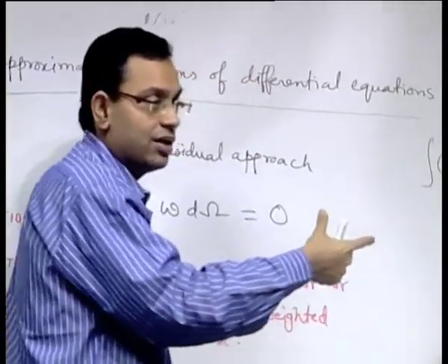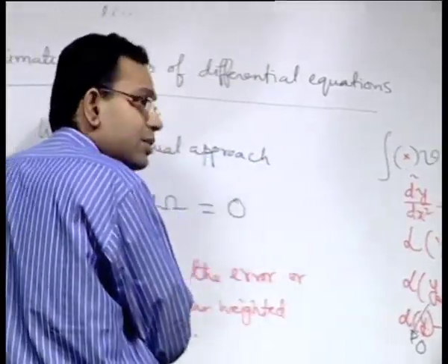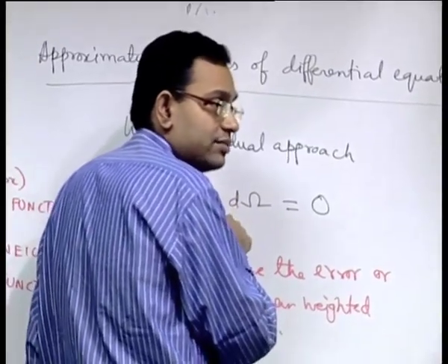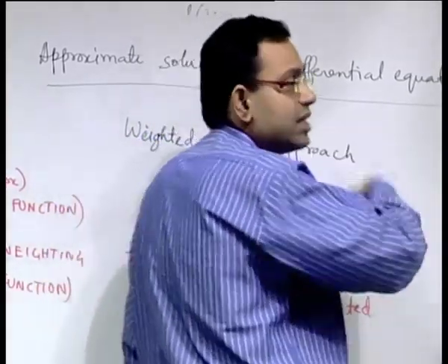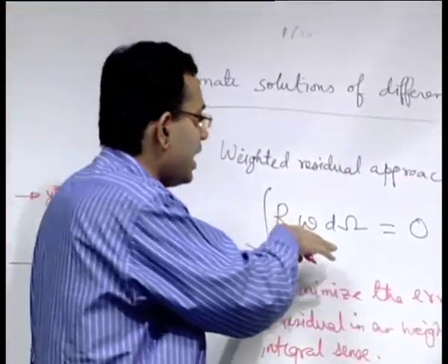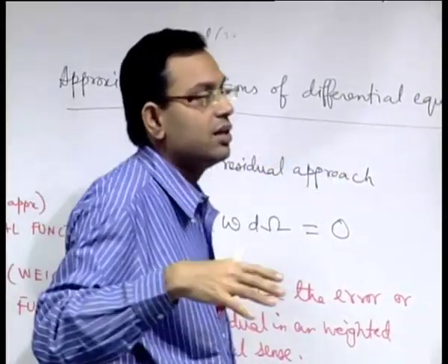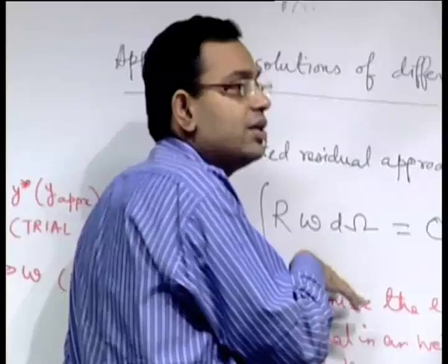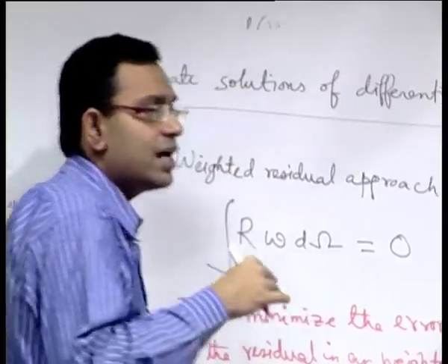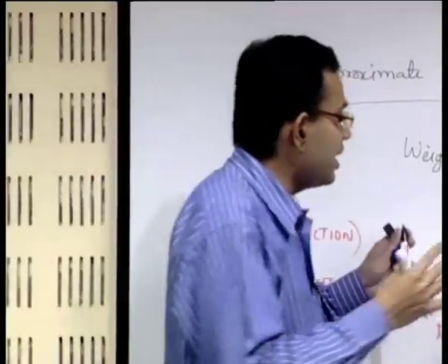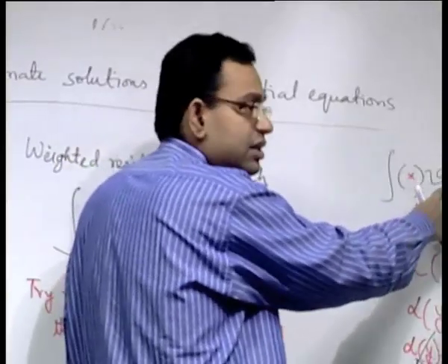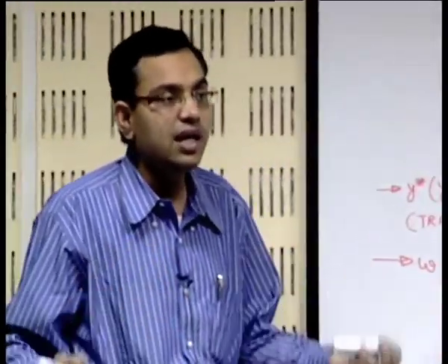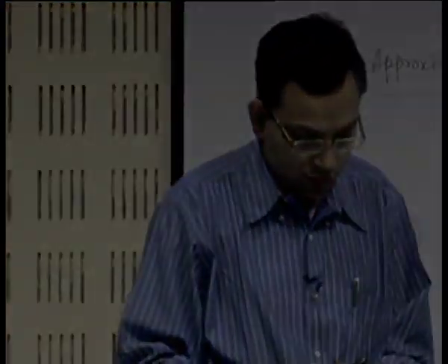So, these are the two relaxations that we have made. We have not substituted the actual function, we have substituted the approximate function instead, and we have not substituted variation in the variable, but we have substituted an arbitrary weighting function instead. But otherwise this formulation has a great similarity with the variational formulation. One advantage of this is that here you do not require the functions to satisfy special conditions like symmetric, positive definite, all those things, because we will not in general be simplifying these by using integration by parts. So, these functions will require some other special requirements that we will see in the next class, but we can see that these functions are not as rigorous as the original solutions and the variation, and therefore it will lead us to approximate solutions of the differential equations. How it can lead us to that we will see in the next class. Thank you.